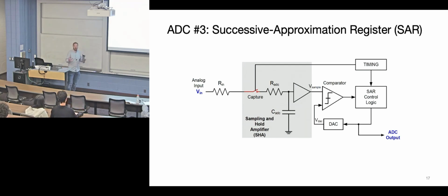Okay, so now we're going to go and try and find a happy balance between the two of them. There are many types of ADC architectures. Oh, those integrated circuit designers want to keep making them up. And PhD theses are being written about them. But then we also have the standard ones that work every day, or solve the general case problem. So this is one of those examples. It's called a successive approximation ADC, or SAR. I always have to remember every year what SAR stands for after 20 years of using them. I forget what they actually stand for.